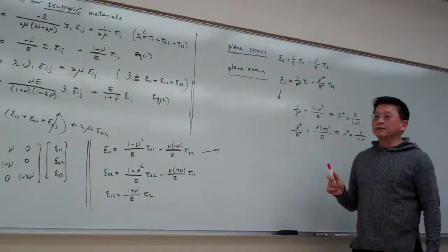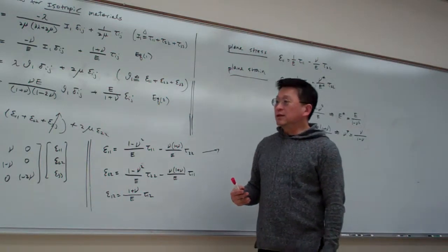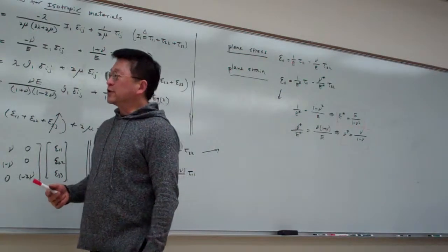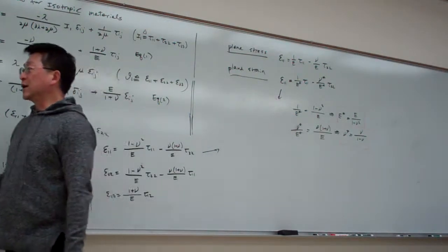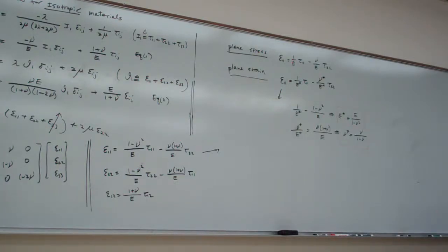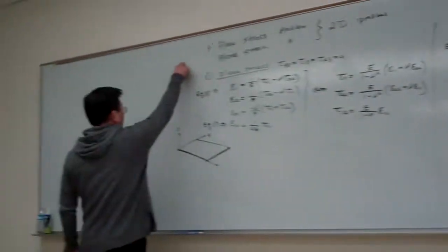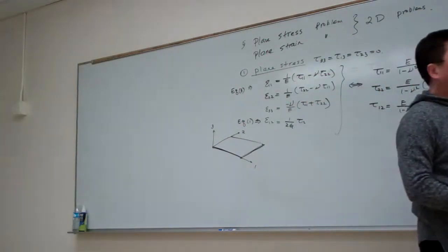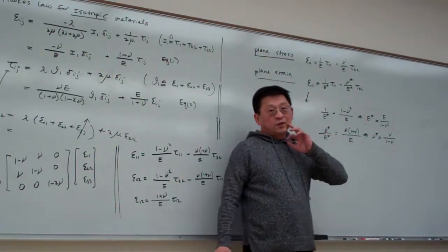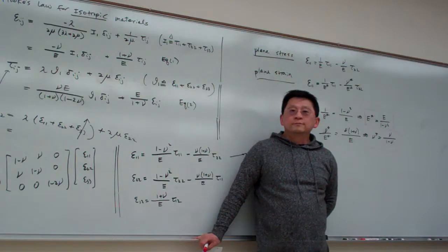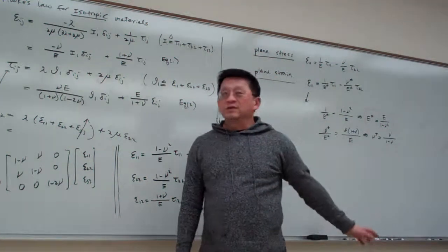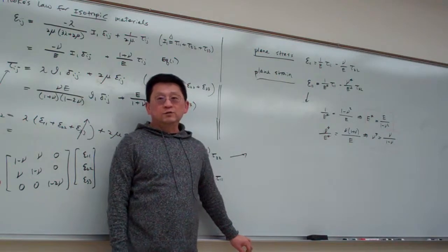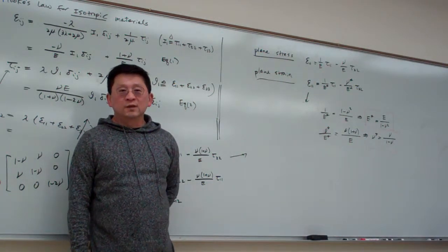So many times when people are doing analytical research, they are usually lazy like me. I only say, oh, that is a plane stress problem. But if the model has a very huge Z dimension, then the problem can be right away converted to plane strain by simply replacing the parameters like this one. That is shown in the papers. Good. And this basically marks the end of the big chapter on Hooke's law, stress-strain relations. So we can finish this.